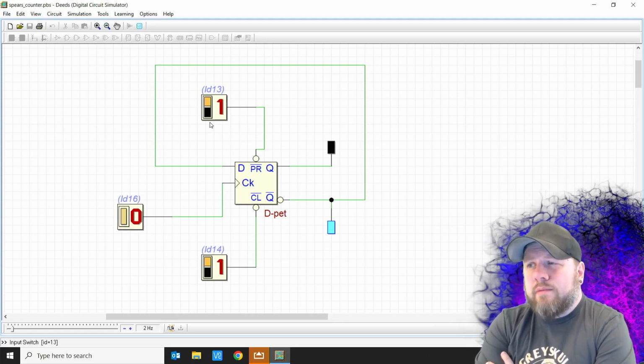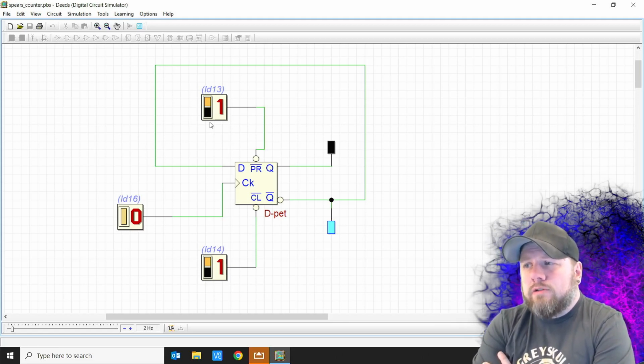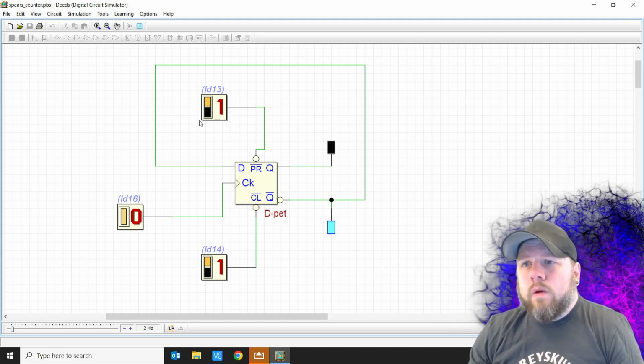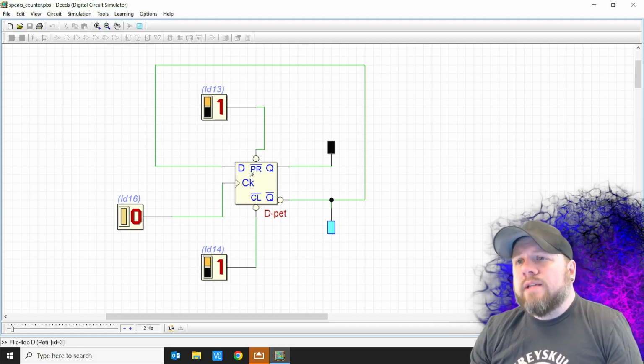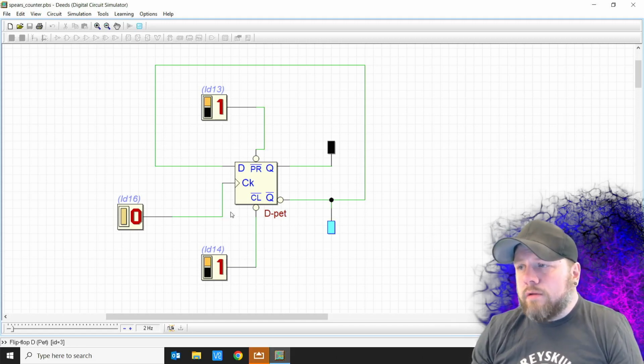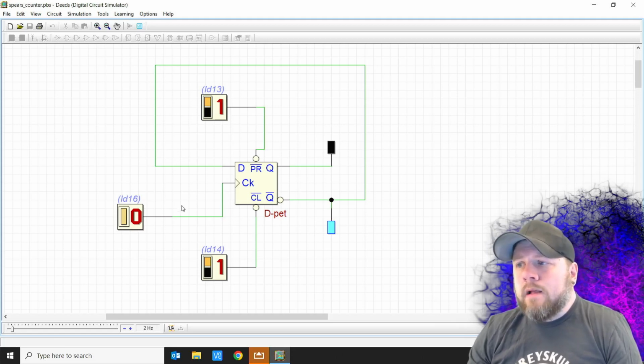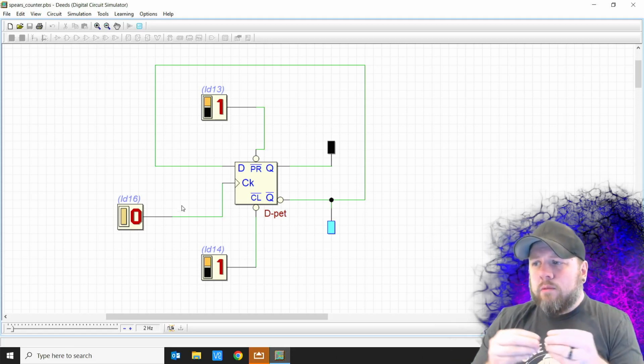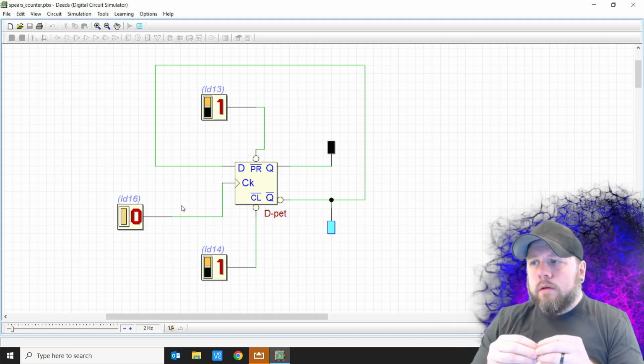And since we have that slight propagation delay, the 0 we had out here is getting through here. By the time this flips, this has already closed that gate. If you have a 1 and a 0 on the same wire at the same time, you have a problem. You have a short.